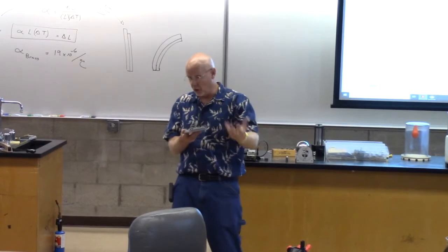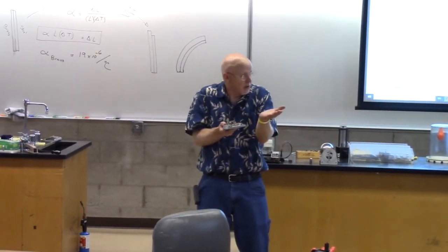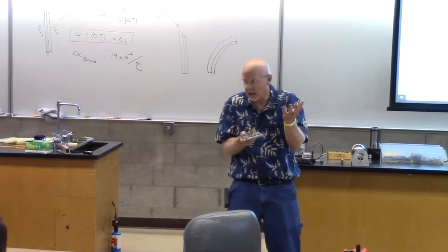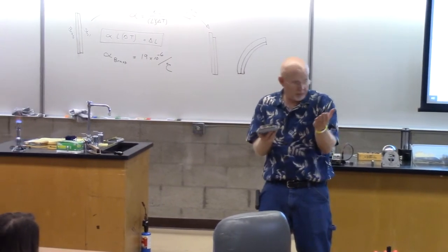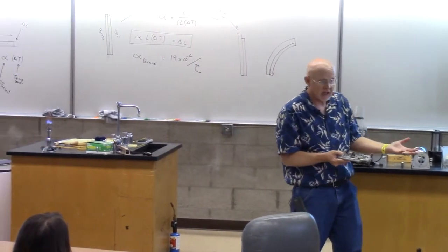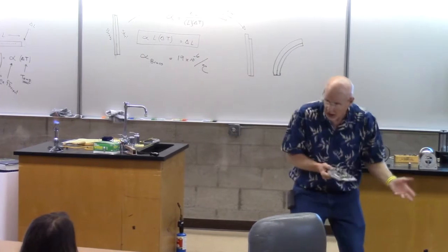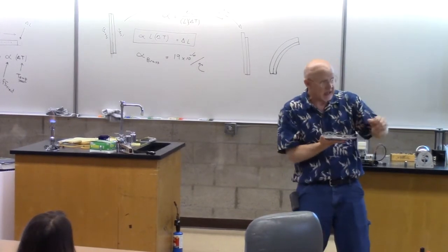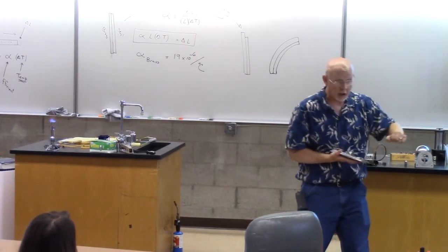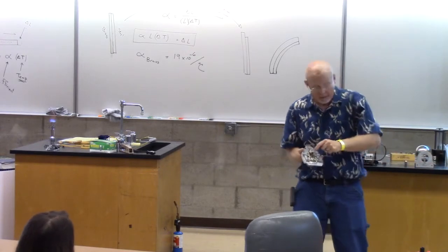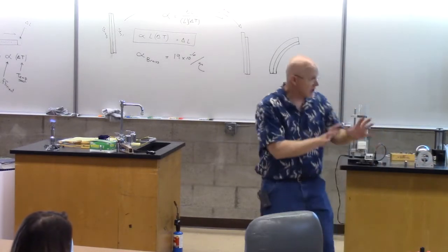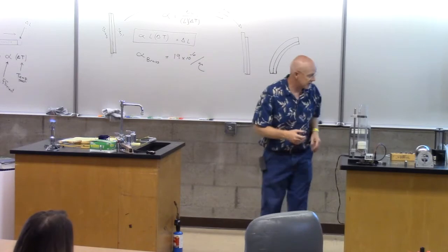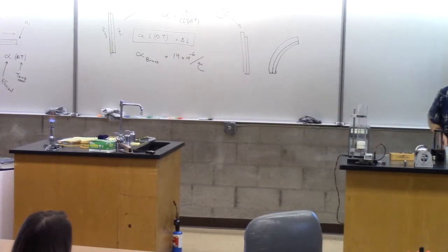So my iron doesn't get too hot, it just shuts off for a little bit. And of course, eventually it cools down, and so the bimetal strip goes down, and so it's constantly making contact, and it's on for a couple of seconds, then breaks contact, and so it's off for a couple of seconds, and then on, and then off, and so roughly keeps the same temperature as I'm ironing the clothes. I don't have to plug it in or not. The bimetal strip uses the advantage of turning it on and off here.